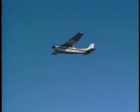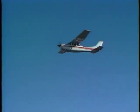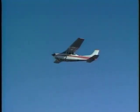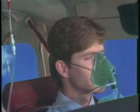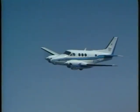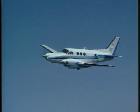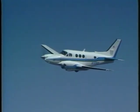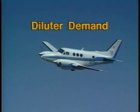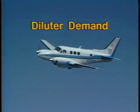The continuous flow system is adequate up to 25,000 feet. Above 17,000 feet, however, you must be careful to maintain a tight seal between the mask and your face. Above 25,000 feet, you and your passengers should use some form of demand oxygen system. The diluter demand is one of these systems and is the next one we'll discuss.